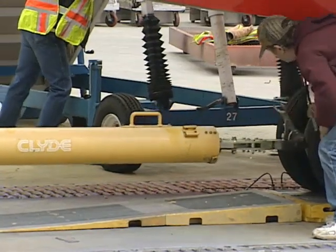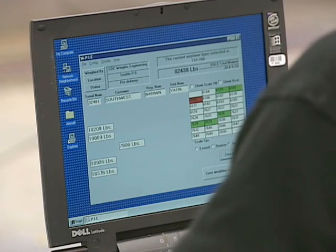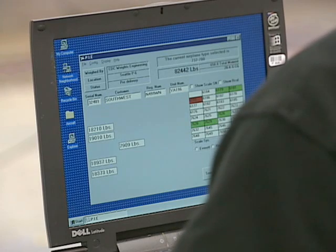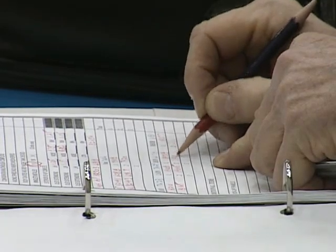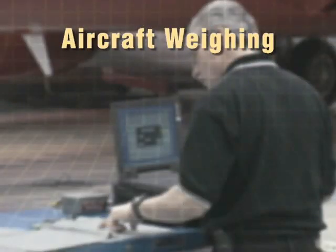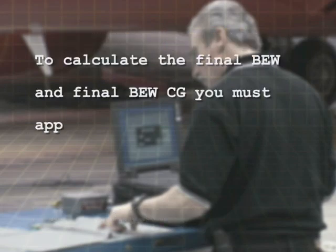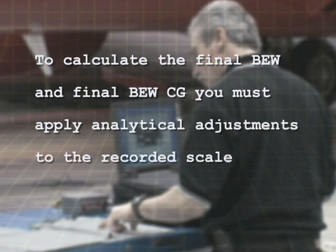Errors in repeatability may be a function of having the hangar ventilation system on, or errors in preparation before taking readings, such as not removing all non-airplane equipment before weighing. Or there may be intermittent problems with the weighing equipment. Repeat weighing until two successive weights and CGs agree within tolerance and record the first of the two readings. This will be the recorded scale weight and CG that provides the basis of the basic empty weight and basic empty weight CG.